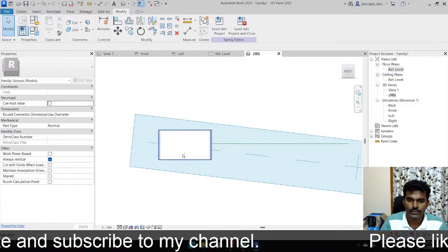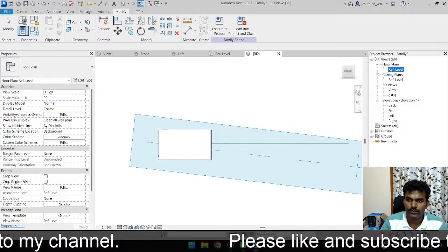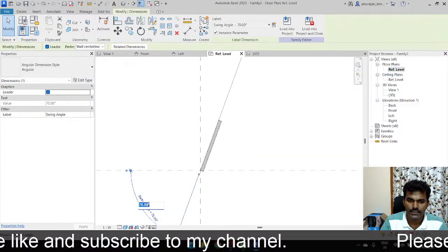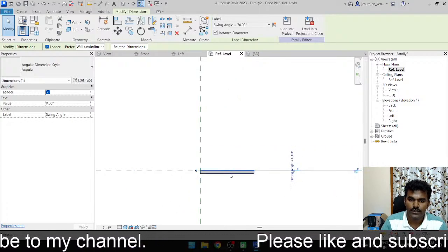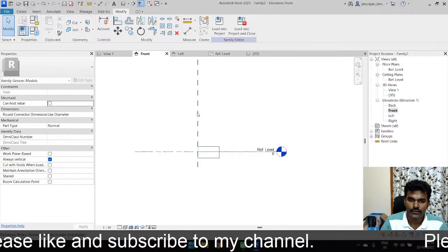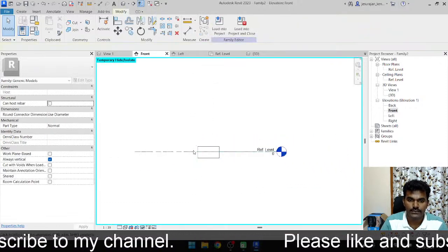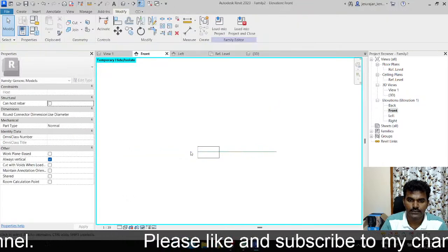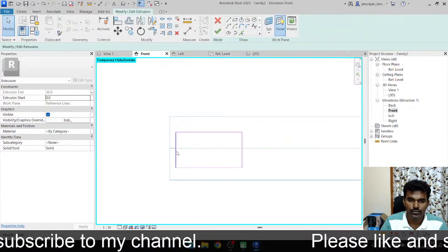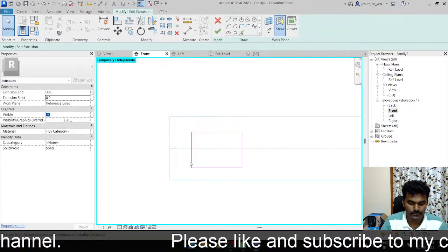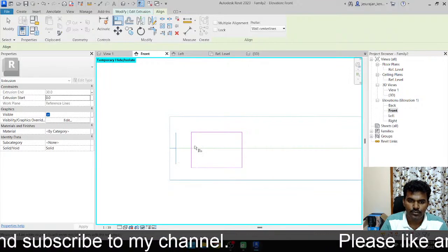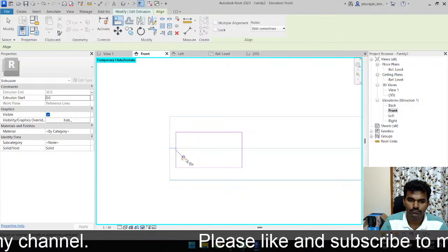So what I'm going to do is go to reference level. Keep the swing angle as 0. Now you can go to front elevation, hide these lines. I just want this much. So now I can lock, align with this point, select the point and select the line and lock.